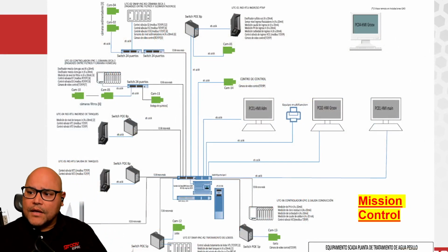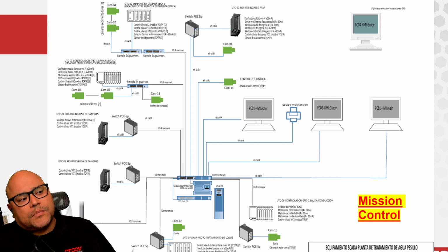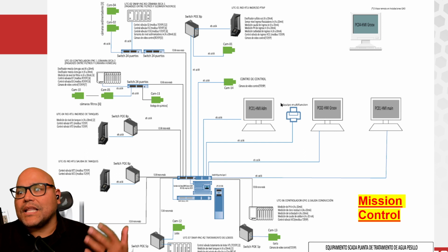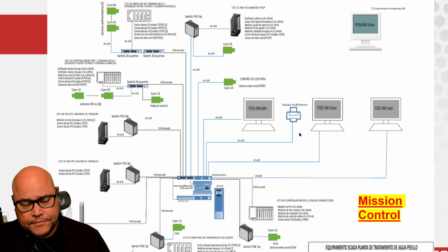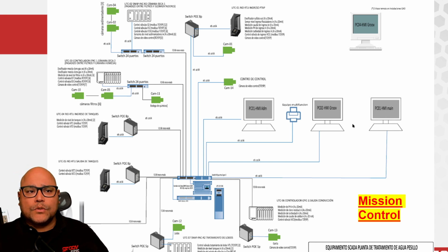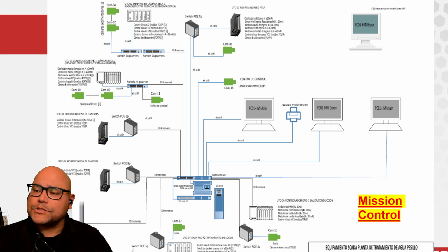Here you have what I refer to as mission control, but this is the water treatment plant. The water treatment plant has various Opto 22 products. It's all different lines of Opto 22 products. So besides the two EPICs that you hear me talk so much about here and here, we also have some local I/O controlled by Rios or by even our older PAC generation that you see here, all communicating to local HMIs where you could do any type of supervisory control, alarming, reporting, etc.